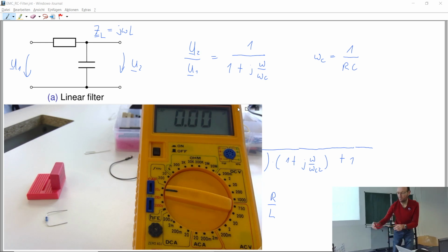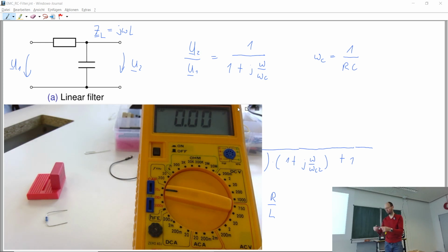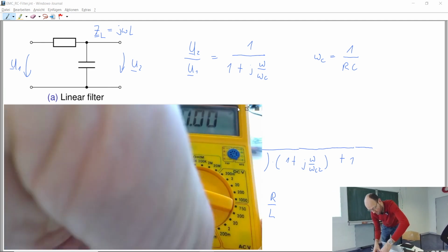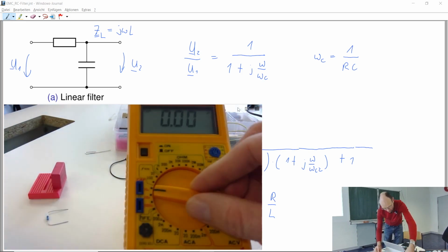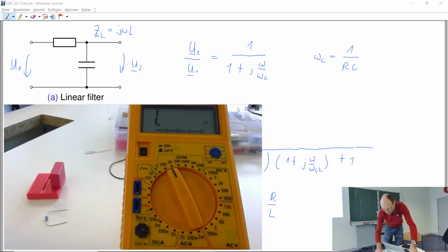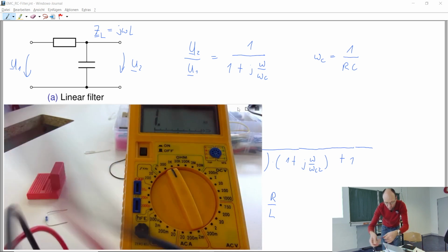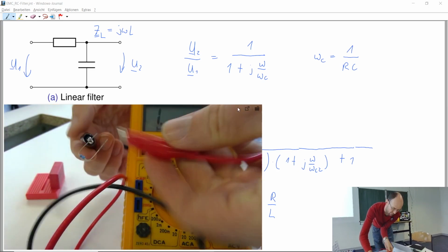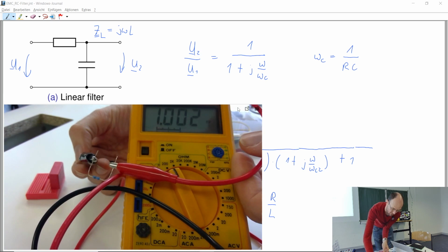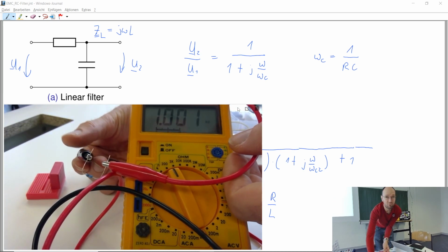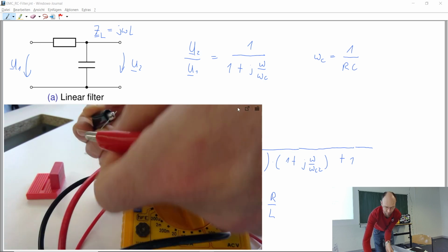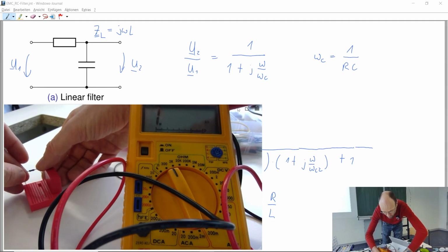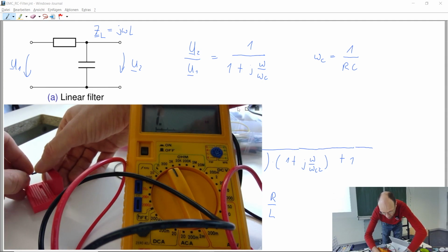And this time I also have measurement cables for the multimeter, and we can switch to the range to measure resistances, 2 kilo ohm range, and measure the resistance of this resistor, and then you can see it's fitting fairly nice to 1 kilo ohm. Okay, so connect the resistor once again to this breadboard.